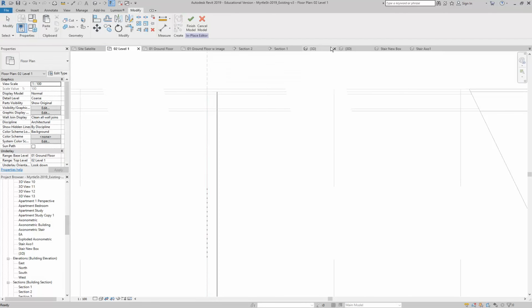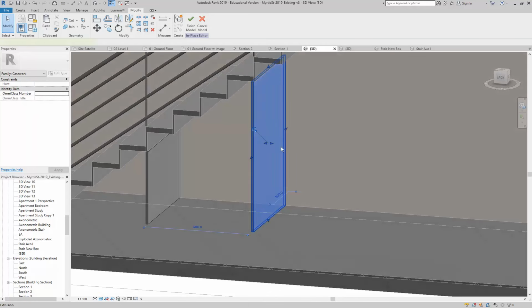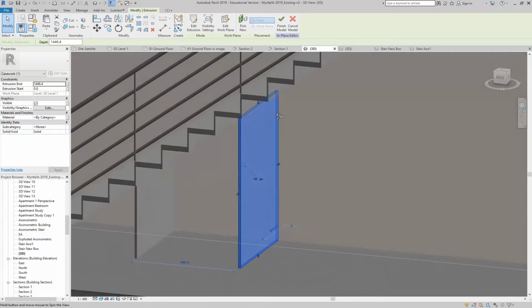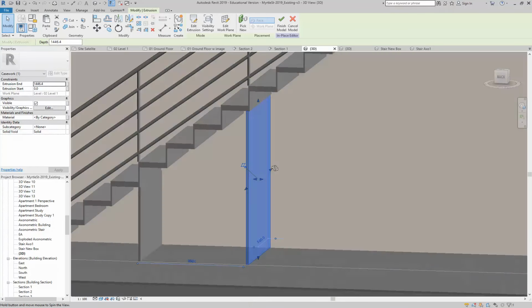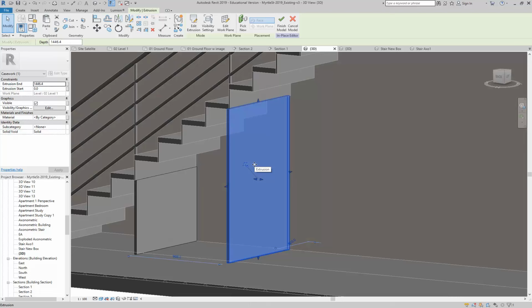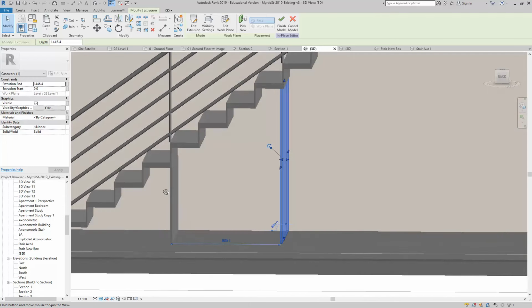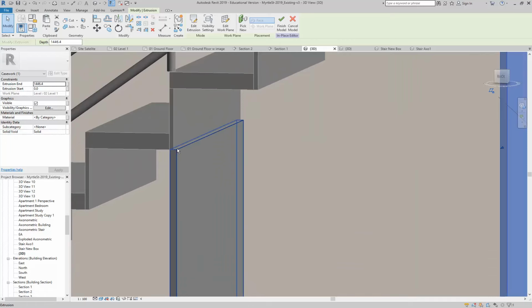And then checking in 3D, so you can probably tell already, the key with a program like Revit, unlike SketchUp, is that you have multiple views. You can always check things in one view and then go to another, and the views are already set up for you. They're all stored in your project. You don't have to keep changing your views. And it's important that you do look at different views because the plan view is only going to tell you certain things, and the heights and the way things line up is only going to come from 3D. So you can see these things look like they're lining up in plan, but in 3D we can see they don't actually line up perfectly.